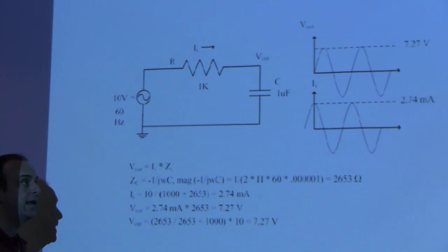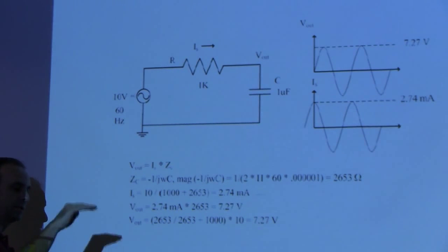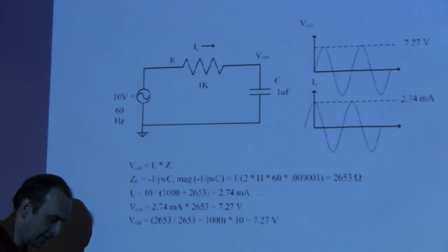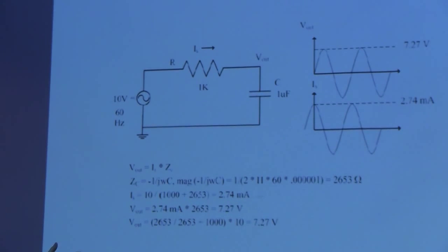You know, am I communicating at 10 hertz and therefore I'm well below 60 hertz and its harmonics? Or am I communicating at megahertz, so I'm well above the 60 hertz and its harmonics? So I got to look at the spectrum and say, what do I care about? I want to get what I care about through successfully.